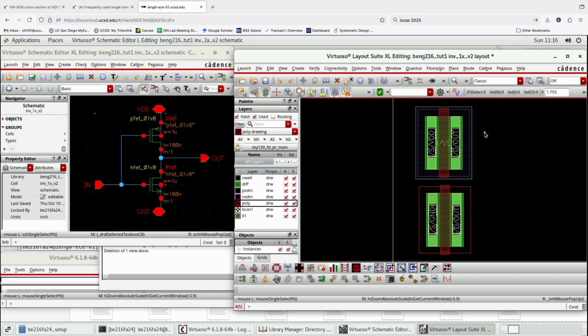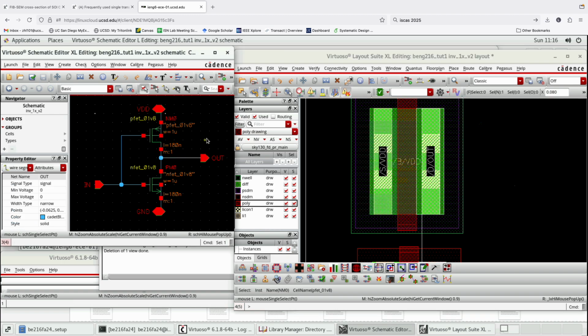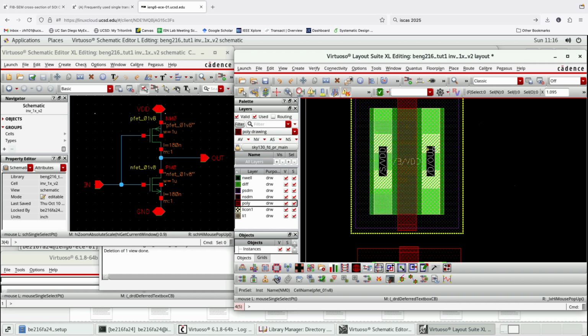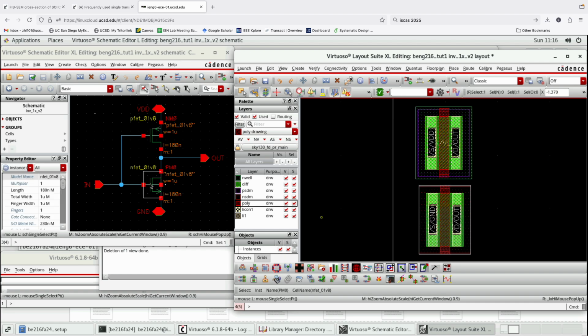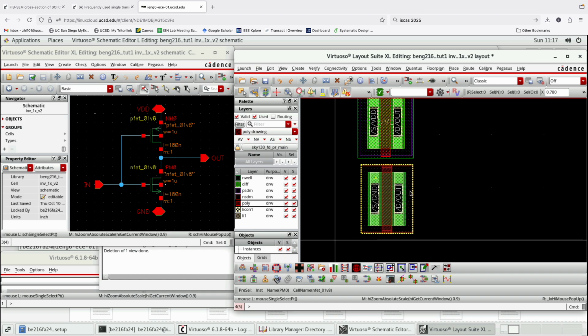So let's take a look at these transistors first. So as you see, this is the PMOS, this is the NMOS. So for the PMOS, because we imported the design from the schematic, we have the source as VDD, bulk as VDD as well, which is this guy, and drain as out, which is this guy. So you see everything here, the net also corresponds to what you implemented in the schematic, which is very helpful because you know which wire goes to where. Same thing for the NMOS, right? But you see that there's actually no connections so far. There is nowhere that we can place our